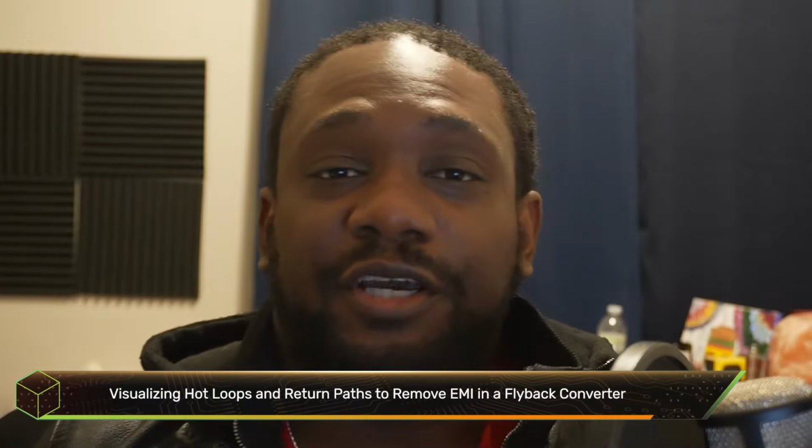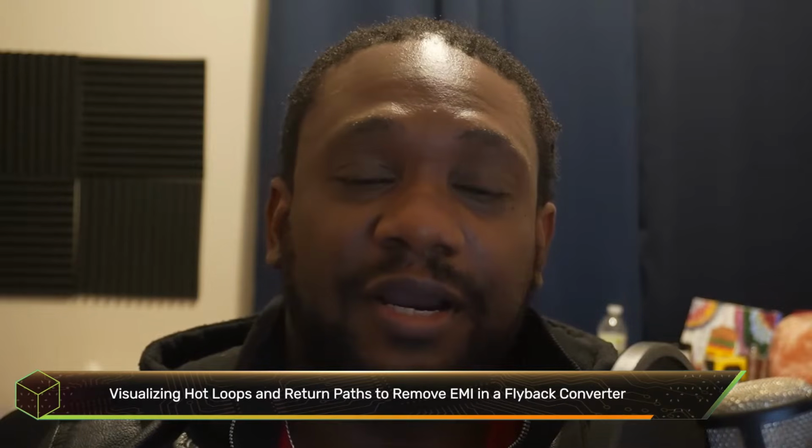Hey, I'm Kirsch. Today we're going to be covering the flyback converter and why it fails EMI, and how you can do layout properly so it doesn't fail EMI. The biggest issue with flyback converters, power switching converters, is they fail EMI because of large hot loops, and I'll explain what a hot loop is later in this video, and also broken return paths.